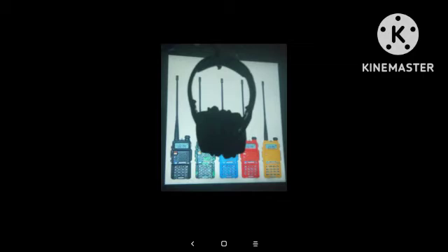Number 29. Approximately how long is each side of a cubical quad antenna driven element for 21.4 MHz? 3.54 meters or 11.7 feet. Number 30. Approximately how long is each leg of a symmetrical delta loop antenna driven element for 28.7 MHz?